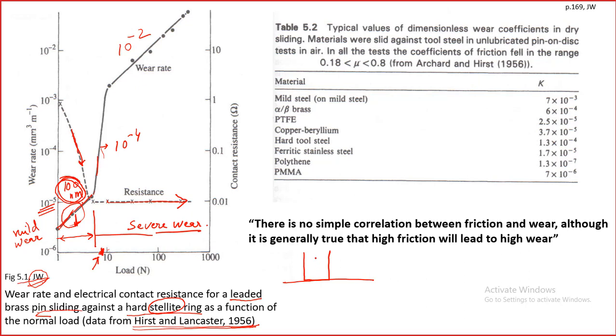For example, it is used for metals only: metal 1 and metal 2. Let's say the wear process is happening, so there is interfacial sliding going on here. What people do is connect this to a voltmeter and pass electricity. Because two metals are in contact with each other, obviously there will be electrical passage, so we can measure the resistance of this contact.